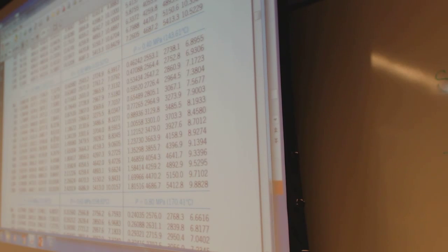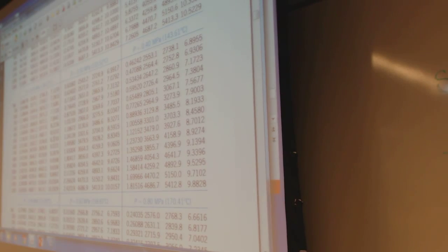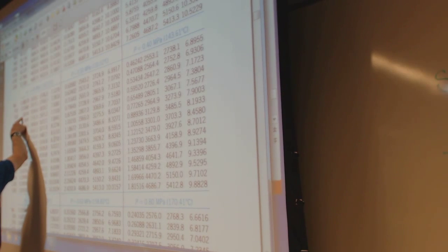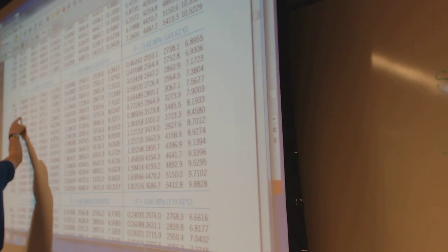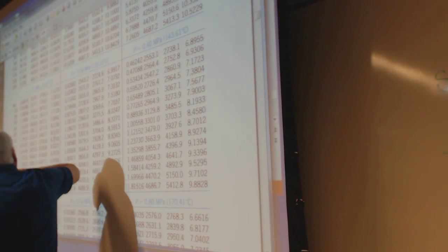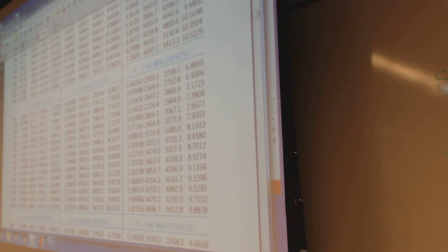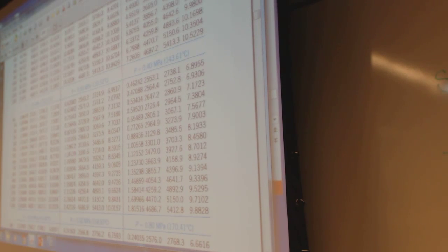So at 200 kilopascals, which is 0.2 megapascals, that's this one, and we're at 200, so we're all vapor because we went above that, so we got 1.08049. That first column is specific volume. So 1.08049 meters cubed per kilogram. Now from that I can figure out what mass I'm dealing with.